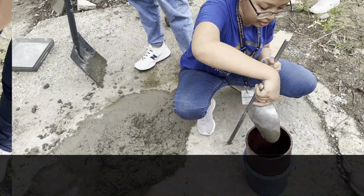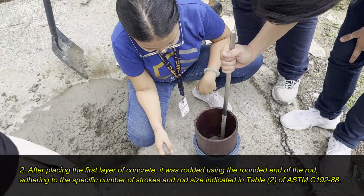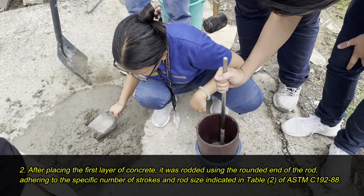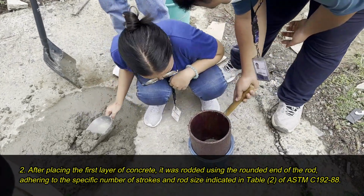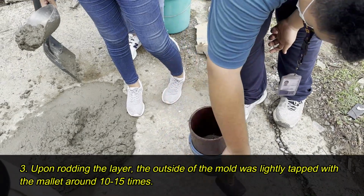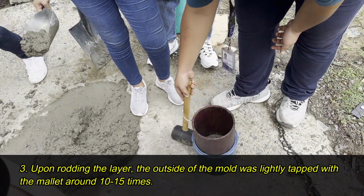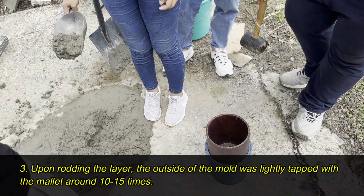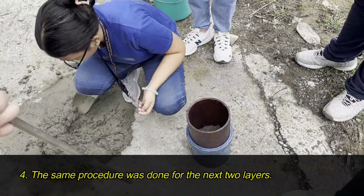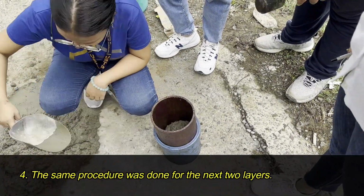Number 2. After placing the first layer of concrete, it was rodded using the rounded end of the rod, adhering to the specific number of strokes and rod size indicated in Table 2 of ASTM C192-88. Number 3. Upon rodding the layer, the outside of the mold was lightly tapped with a mallet around 10 to 15 times. Number 4. The same procedure was done for the next 2 layers.